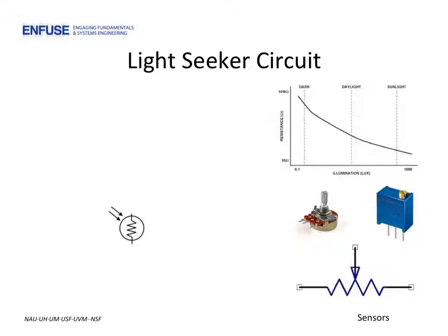As we discussed earlier, and we can see from this graph, the photoresistor takes on a wide variety of values. Furthermore, if you don't have a calibrated photodetector, you won't readily know in advance what light intensity you want to turn the light on. As such, you'll want to design initially for a lot of flexibility.